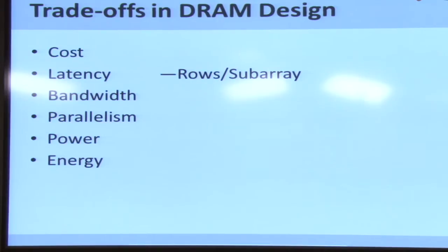Which essentially allows it to, which is why we need that prefetch, right? If I'm sending out only 8 bits of data, I could have very well made my bank I/O also 8 bits. But I need to fetch 64 bits because that's when I can match the bandwidth of the external bus.